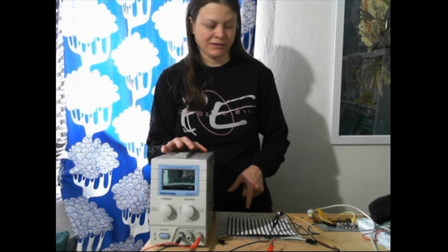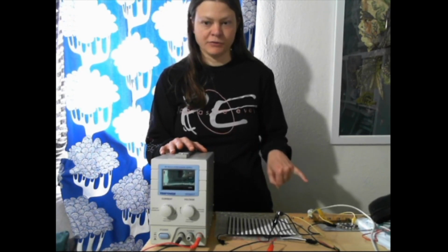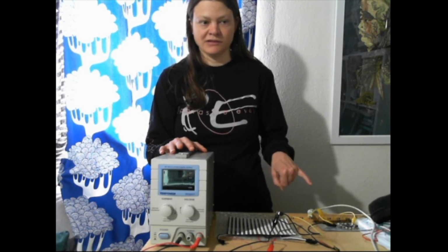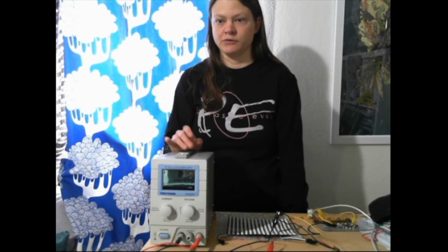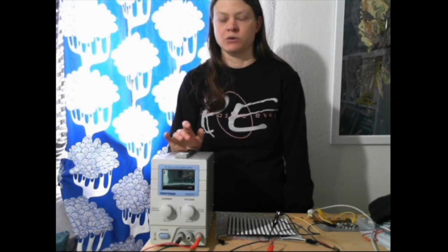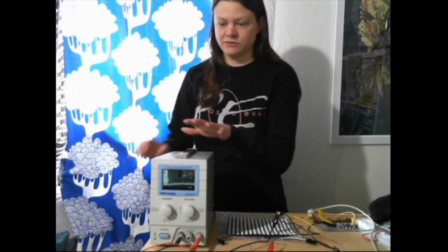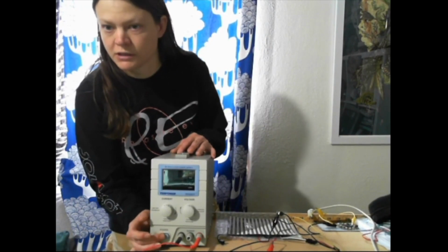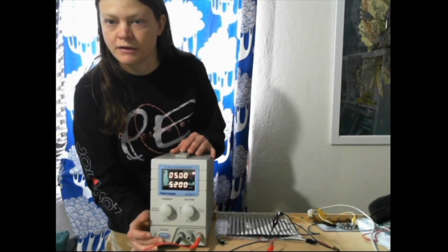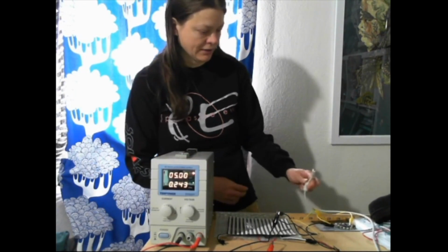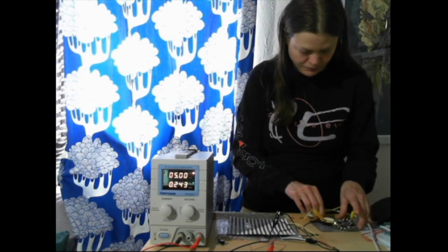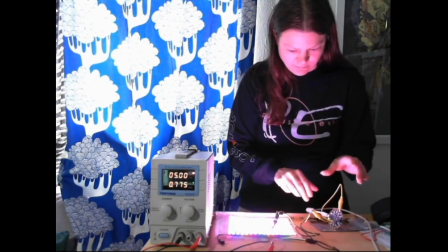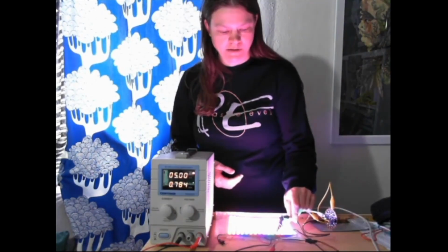If you have too many lights plugged in, like running them off the board without external power, it's very easy to make your Arduino freeze up because it can't power itself. So we're going to turn the power supply on first, turn it on or plug it in. And then we're very carefully going to plug in our microcontroller, just like this. Boop. And there you have it, it lights up.